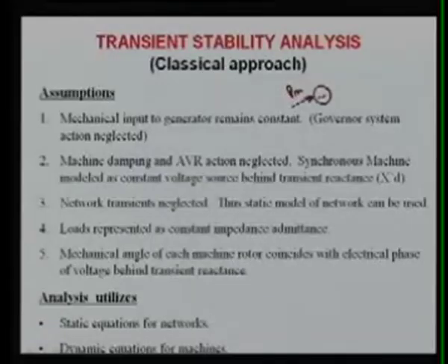By that time, the governor action or prime mover action is almost negligible, because the time constant of this is very, very high. So we can ignore this, meaning the mechanical power input to the generators remains constant. The second assumption is that the mechanical damping, that is the machine damping D, and the AVR action are also neglected, meaning the automatic voltage regulator action is also neglected.